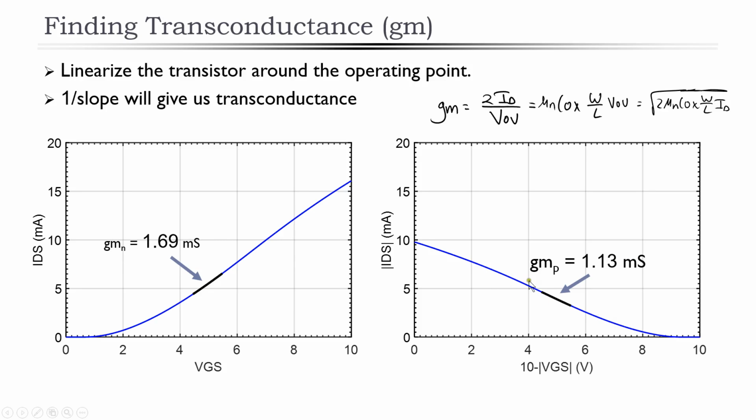But there's also another thing to note: this curve doesn't maintain the square law behavior all the way for very large values of VGS for the NMOS. This is due to the mobility degradation of the device. You can actually degrade the mobility of the carriers in an NMOS and a PMOS so much that increasing the VGS no longer gives you the square law region, and it ends up being linear. If you look carefully, in fact, it starts degrading. But that's a topic for a whole different episode.